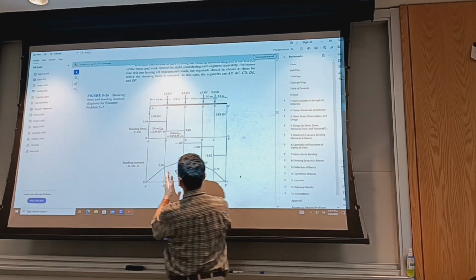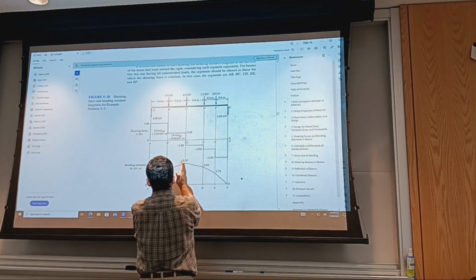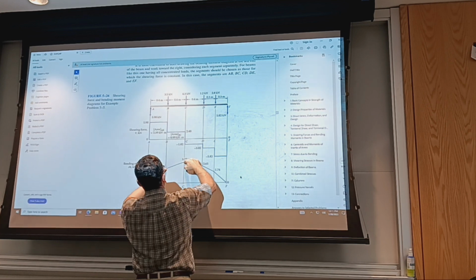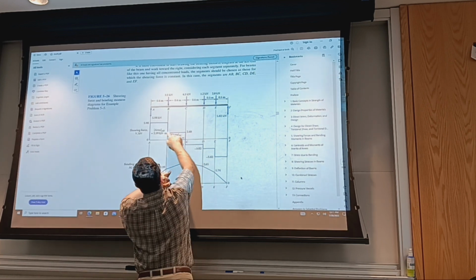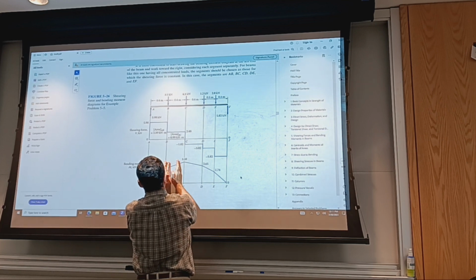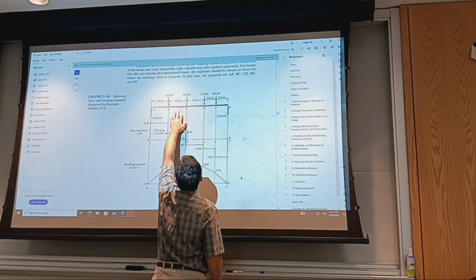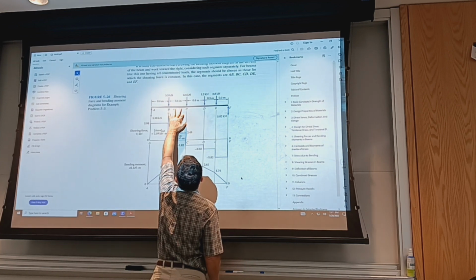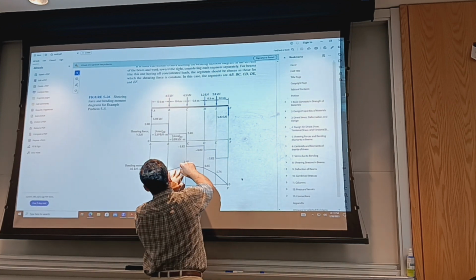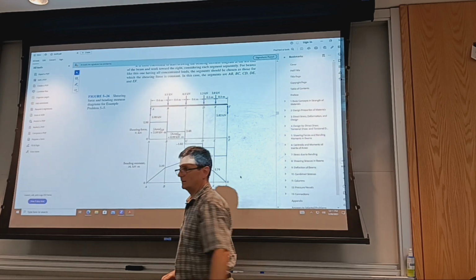If I want to know the change in moment between 2 points, could be where things happen or could be elsewhere, the change of moment from here to here is going to be this area. Say for some reason I want to investigate 0.1 of a meter somewhere here, the change of moment will be equal to the area corresponding to that interval.